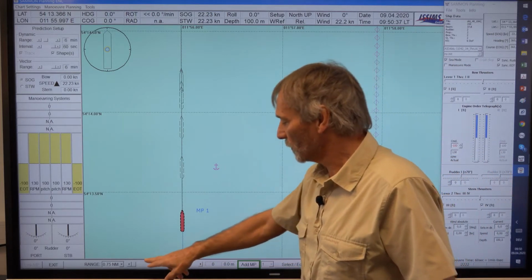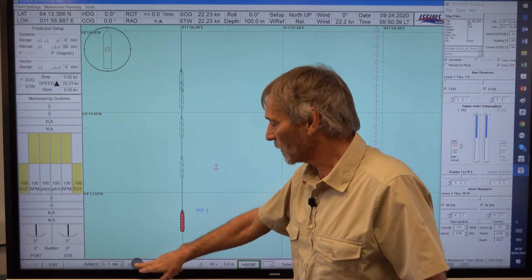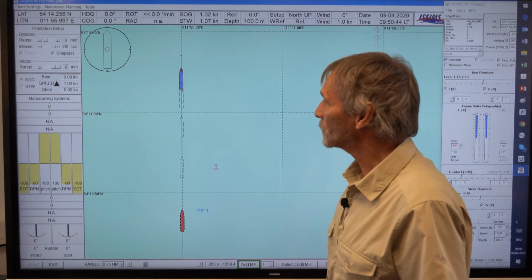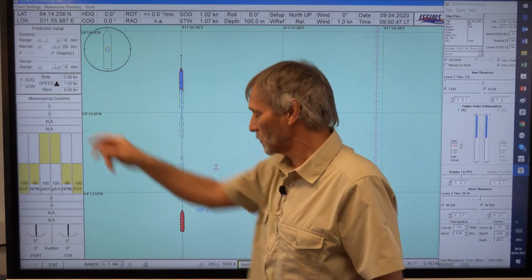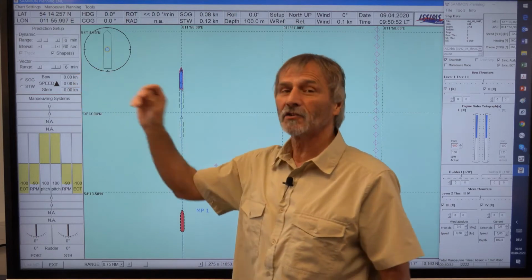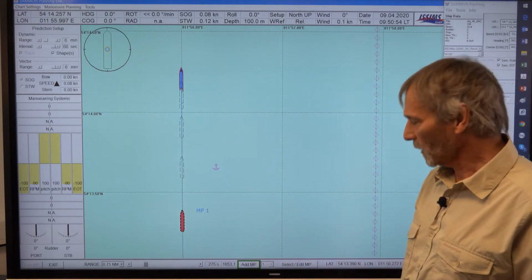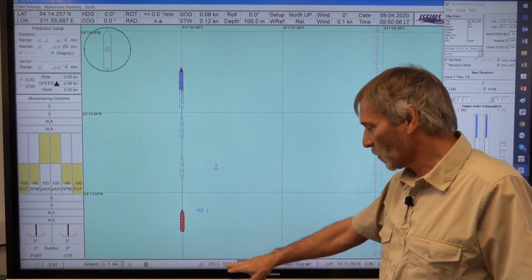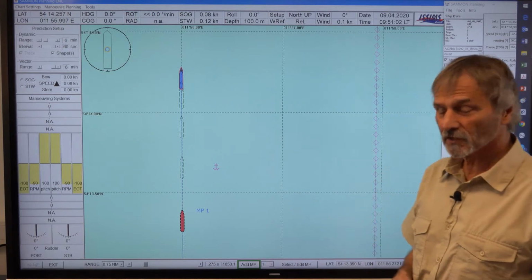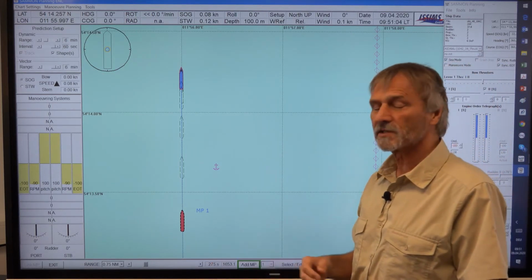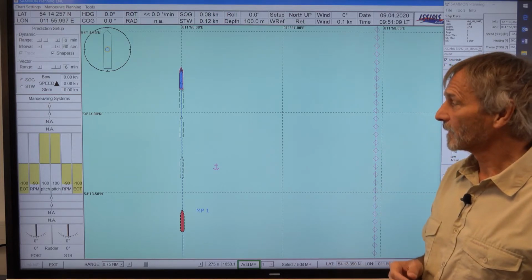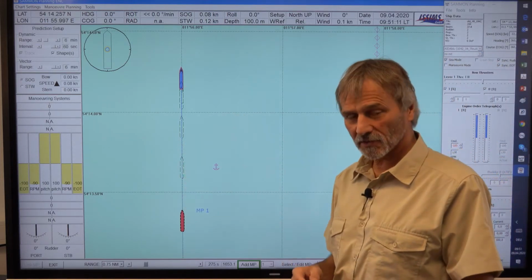For this reason, we move our ship with this magic time slider to the position where the ship might have 0 speed. For the time being, it's 1.2 knots, a little bit more. So now we have 0.08 knots, nearly stopped. And we can read here the distance, 1653 meters, and it has taken 275 seconds. Okay, this is our stopping distance.